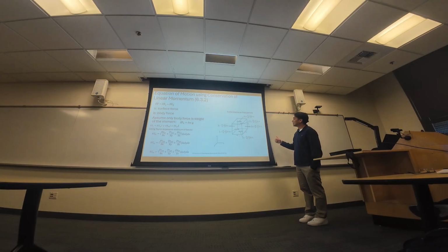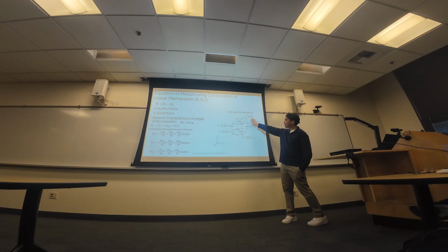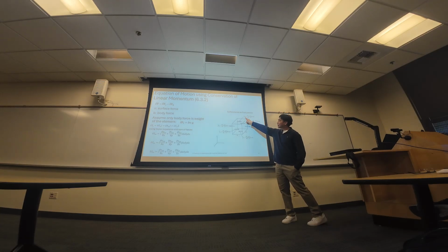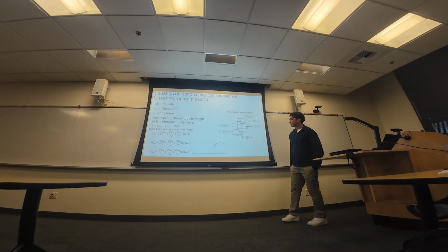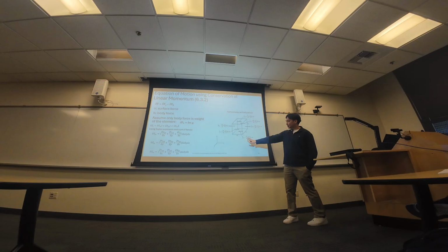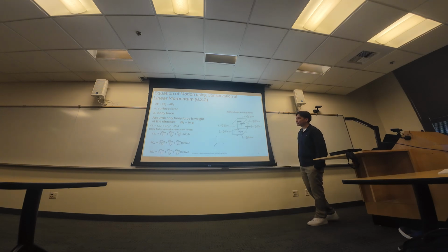This one is shear stress, right? So you're working off the y-axis, but your second subscript x is in the x direction. So with these 2 subscripts, the first letter is the axis, and the second letter is the direction.